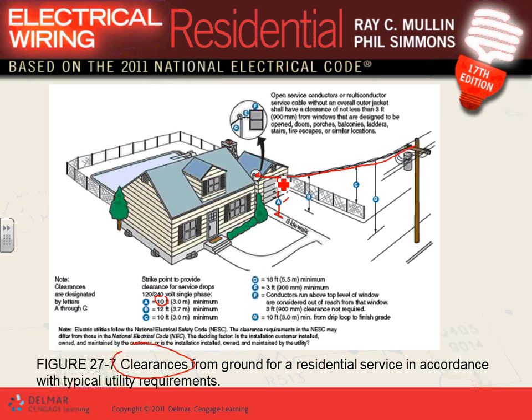If you go over a driveway, a residential driveway, or commercial driveways with voltage 300 volts or less, like 240/120, 208/120, the clearance is right here. This is 10 feet here. This is 12 feet. You go over driveways, you have to clear by 12 feet. Okay? Now, that's the second one.